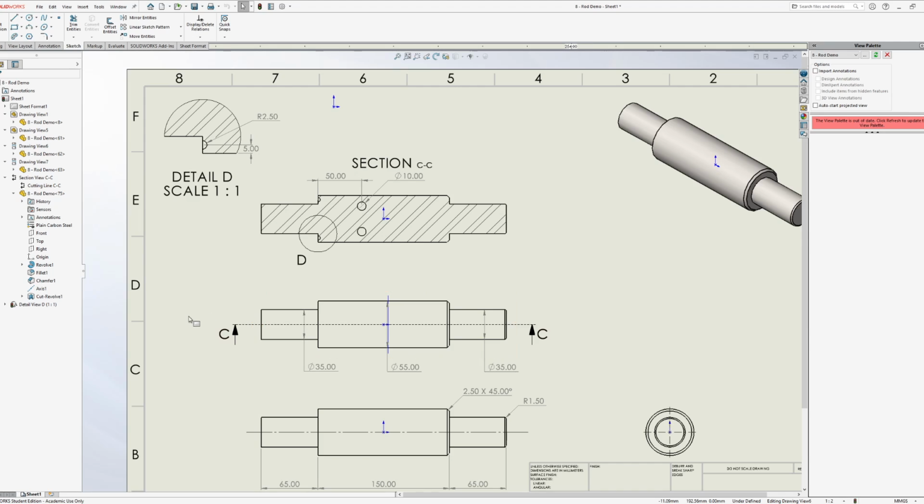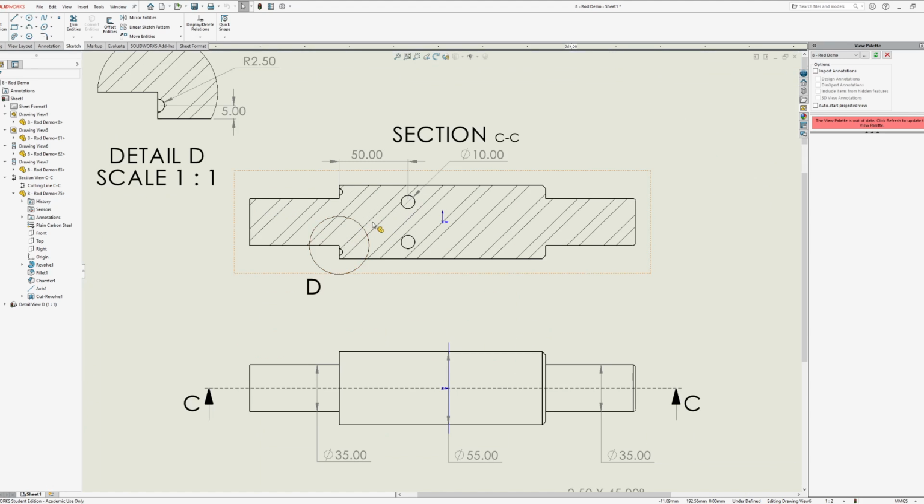this implies right here, the arrows pointing upwards, means that we're looking at the top half of this shaft. So it basically took a knife, cut right through the shaft, and then it's as if we tilted the shaft kind of clockwise. So basically, you're looking directly at the flat face of it now. You're turning it away from you. So then you're able to see inside of it as well.